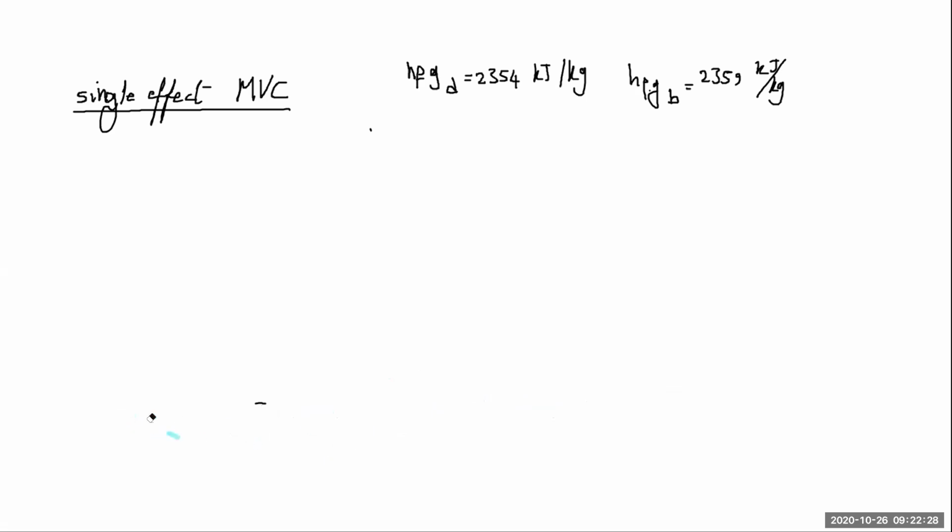Our next step here is Q for the heaters. Change this to the pen. For the heat exchangers, it is m dot feed. We know the m dot feed, we calculated this, 2.5 kilogram per second, Cp feed, which is given to us, and then T feed minus T cooling water. Now, this is going to provide us with the Q for both of the heat exchangers together.